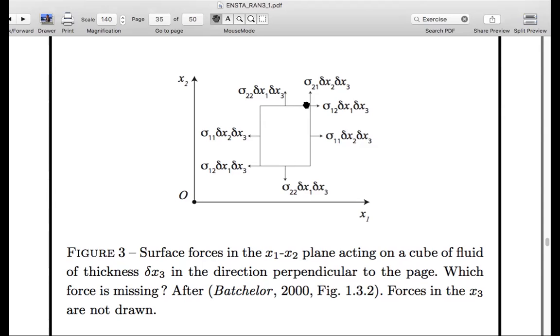So let's start with this surface here. I've drawn its normal there, right? In the X2 direction. And I want to talk about the force in that direction. So that's a normal stress. So I take the sigma 2 2, that's the force component in the X2 direction because of the first 2, per unit area with normal in the X2 direction because of the second 2.